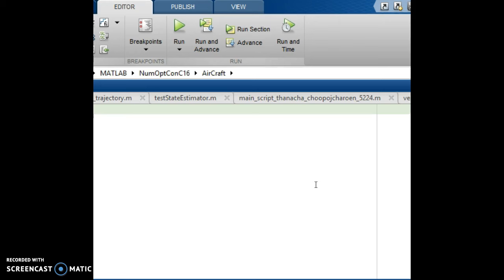The way I simulate this quadrotor is not just saying, okay, plot this position, plot this position. That would be too easy. Of course, I have to model the dynamics, the physics behind it, the differential equation behind the quadrotor. Turns out we need 3 states for position, x, y, z, 3 states for velocity, x, y, z, 4 for quaternions, and 4 for the derivative of the quaternions. So I use quaternions to update the orientation.